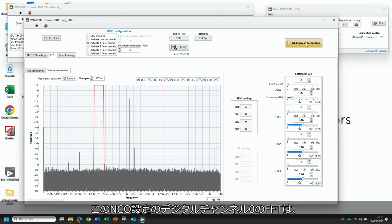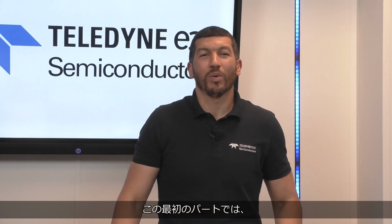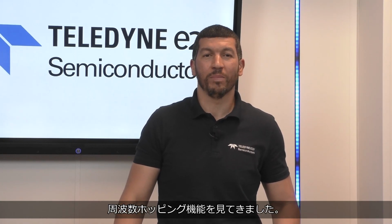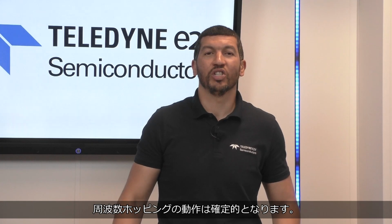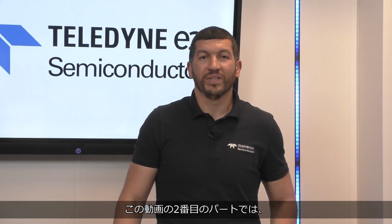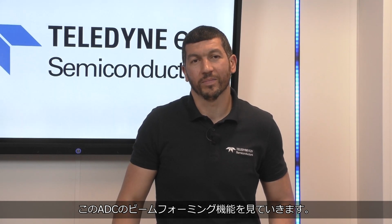You can check the FFT of the digital channel 0 for this NCO configuration on the IQ display and acquisition window. In this first part, we have seen frequency hopping capabilities of the EV10AS940 ADC thanks to embedded NCOs. Even not demonstrated here, the frequency hopping is deterministic when using GPIOs of the ADC. In the second part of this video, we will see beamforming capabilities of this ADC.